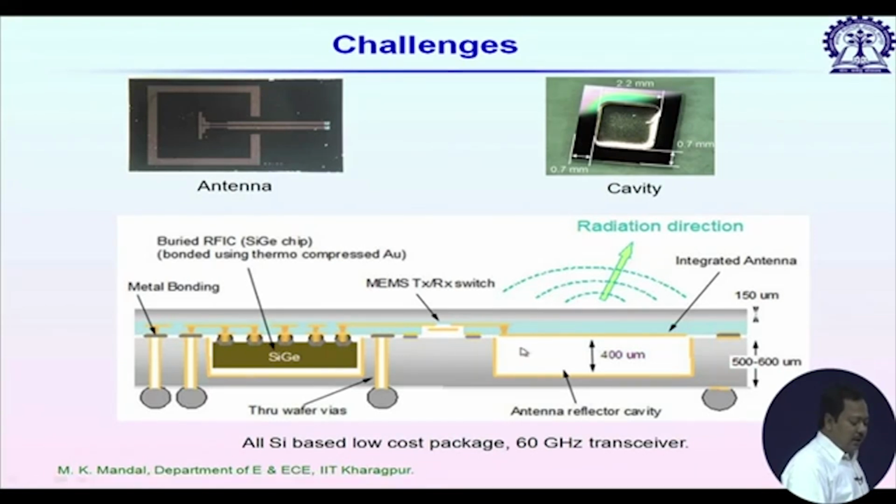So, the antenna should be placed as far as possible from the chip. Not only that, if there is any metal part on this chip itself, then we have to use some sort of insulator between the antenna and the chip part, or simply increase the separation between the antenna and this chip part.